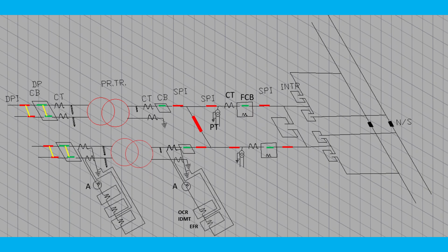With 100 volt ampere and 100 ampere current, across the primary the voltage is only 1 volt, because it is connected in series, so the voltage drop in it is very minimum. But at the same time, on the secondary the output current is 5 ampere, and as it is 100 volt ampere, the voltage will be 20 volt. That is all permissible for panel board working.